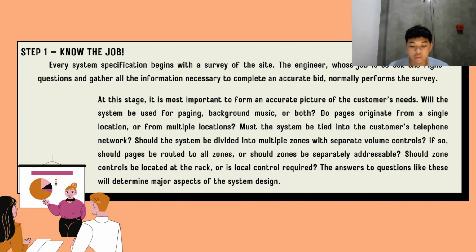Talking to individual users of the proposed system will help to reveal important design details. Is the main reception station located directly under the speaker? If so, then an independent local volume control should be provided for that speaker so that it can be adjusted to allow conversations with patrons while the person issuing pages is sitting under the nearby speaker. If so, then consider equalization or a separate muting circuit to avoid feedback. Is the light switch height a comfortable location for zone or volume controls, or does the user have another preference?